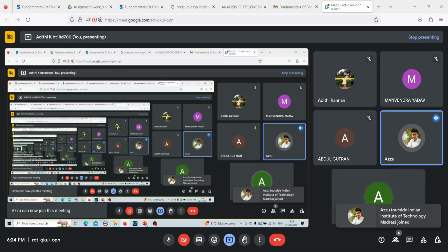So v square, I am converting it into omega R. Omega R can also be given as 2 pi into the rotating speed of the centrifuge given in RPS. So I hope this is clear. Throughout the session we'll be having these tiny numericals.